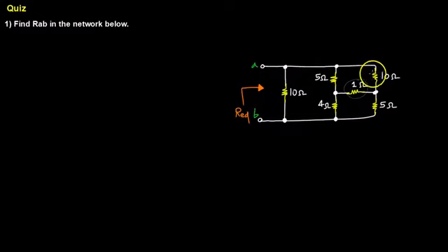So I can look here and see that we have multiple options. We can either work on this delta circuit, and how I know it's a delta is I'm thinking in my head that I have a resistor here, here, and here, not in series, but sort of 3 branches that are connected to each other, and if I bend this guy down this way and the 10 ohm down this way, it's going to look like this, like that.